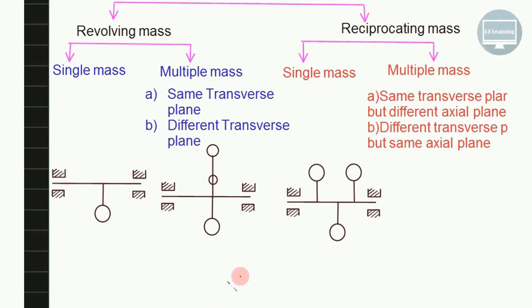So a reciprocating system will be something like this. We have a piston, we have a cylinder, we have a crank and connecting rod. Will this piston reciprocate? This piston will reciprocate, and since the crank is rotating with a uniform angular speed, will it have an acceleration along this direction? Because of inertia, it will produce the balancing problem. And because of this, a reciprocating engine cannot be operated at high speed, because balancing is a major issue.